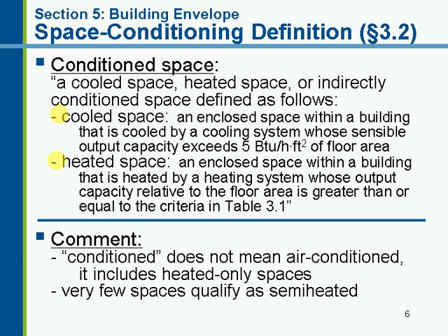As an overview, it turns out that very few spaces qualify as semi-heated. If you think about warehouse type spaces, usually if they're uninsulated, they need quite a bit more heating capacity. Actually, for my study in Seattle, we took a look at some calculations. There were some uninsulated warehouses, with warehouse doors that were not insulated, that had a heating load of about 70 BTUs per square foot.